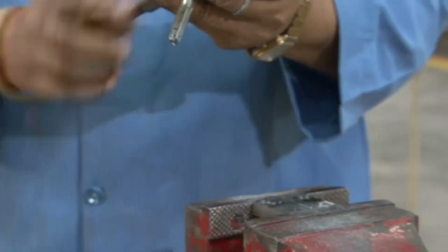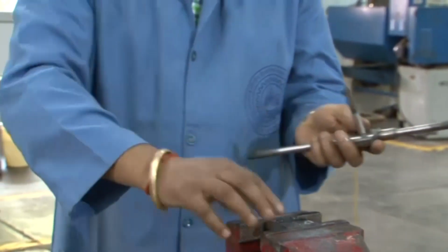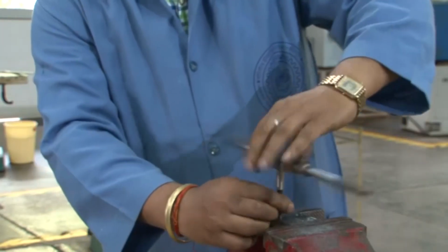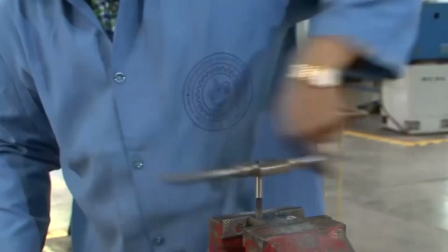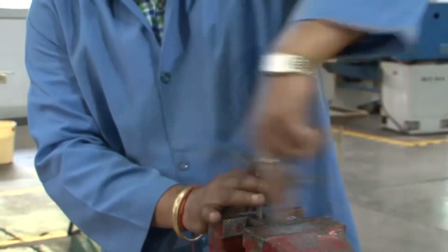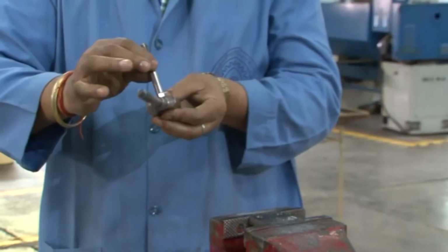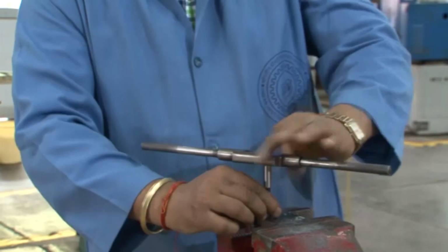That is it. So, the drilled hole is now reamed and tapped. Is this the final tapping? No, this is intermediate tapping. Tapping has to be done thrice. Once is rough, once is intermediate, and the final is the smoother one, where the perfect tolerances, sizes and accuracy of the thread or the threaded hole can be maintained. So, this is the final tapping, to have the final accuracy of the drilled hole.